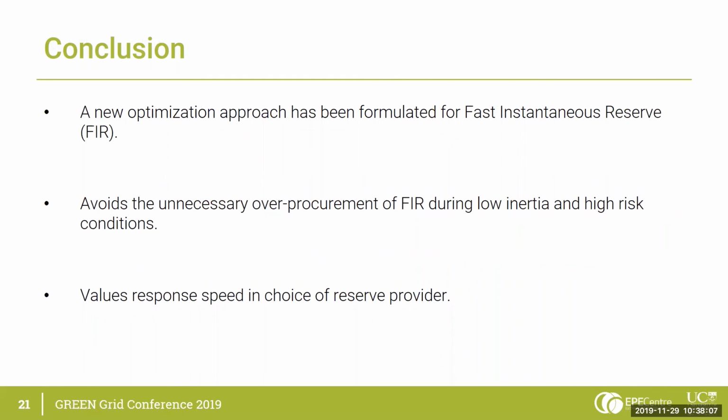So in conclusion, I have developed a new optimization approach that has been formulated for fast instantaneous reserve. This avoids the unnecessary over-procurement of FIR during low inertia and high-risk conditions. And also, since we include those response speeds from those reserve providers, in this optimization we are valuing those response speeds.